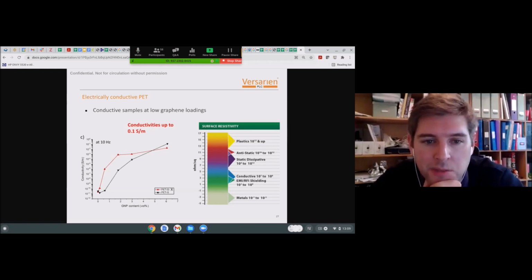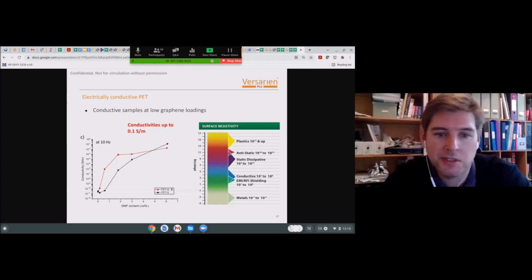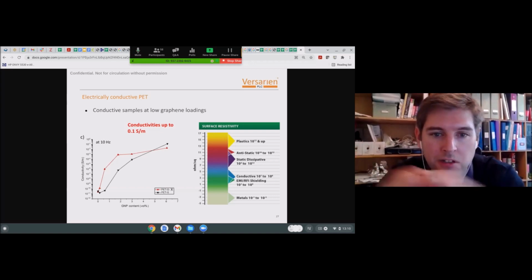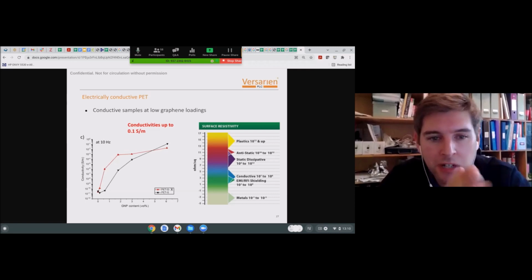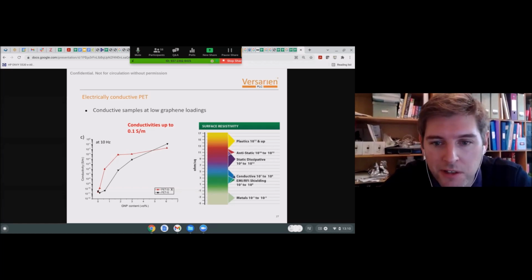So with our graphene polyester fibers, we've been able to optimize the dispersion of graphene. So that's probably the most important thing, when we're putting graphene inside other materials, it's how well you disperse it. You don't want all the graphene in one location and nowhere else. Otherwise, you'll have pockets where you've got some conductivity, then it's insulating again. So ideally, you want a very uniform product that's controllable. And so we're working now within a range where we can maybe achieve some of these anti-static properties.